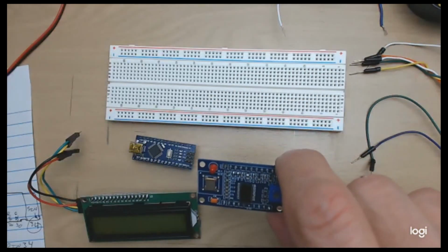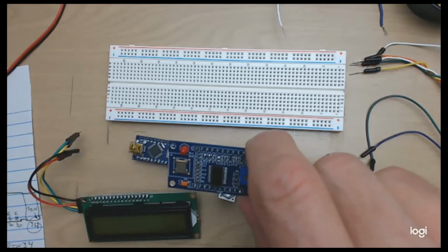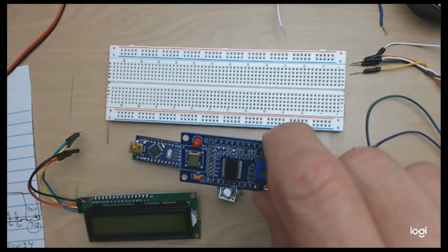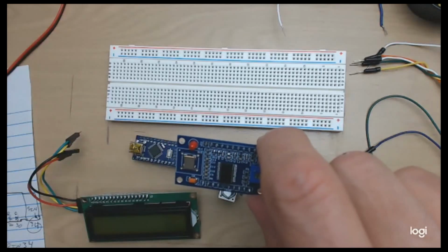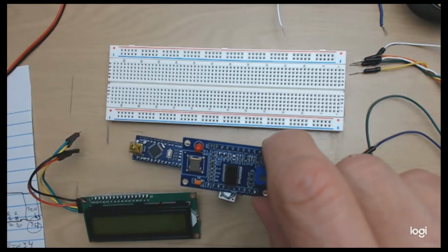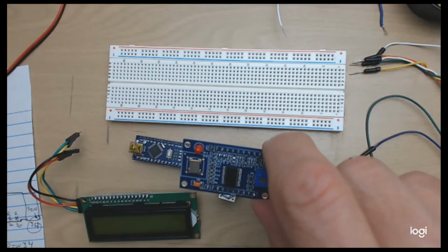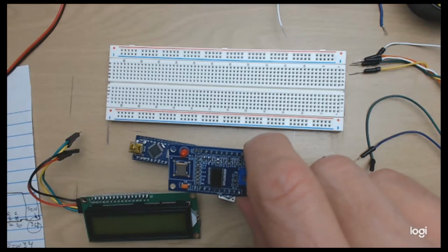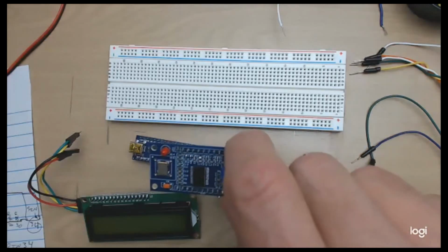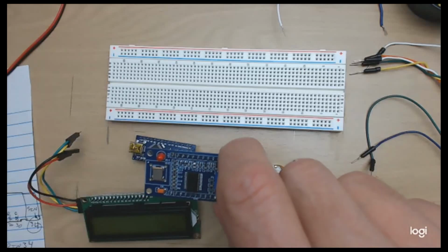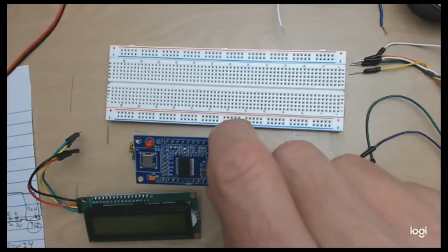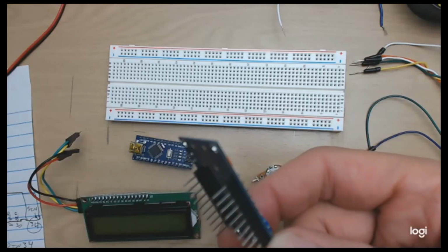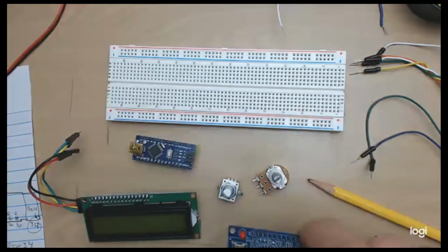This is the AD9850, an Analog Devices 9850 signal generator. It's a clock generator that is capable of producing a calibrated sine wave up to 62.5 megahertz. It can also produce a square wave up to that frequency, although above about 20 megahertz, the square wave gets kind of squirrely and looks more like a mushroom than a square. So that device is the actual clock generator that generates the frequency.